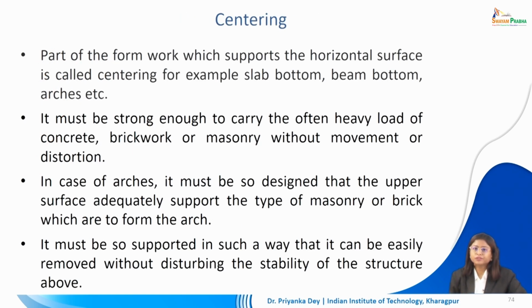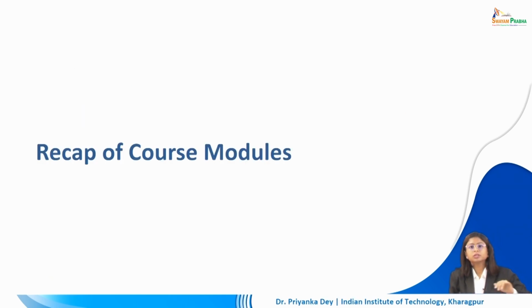Centering is the part of the formwork which supports the horizontal surface. So if you are doing a slab bottom or a beam bottom, arches, then we are doing centering. Now if we are going for vertical, that will be the other parts of the formwork.